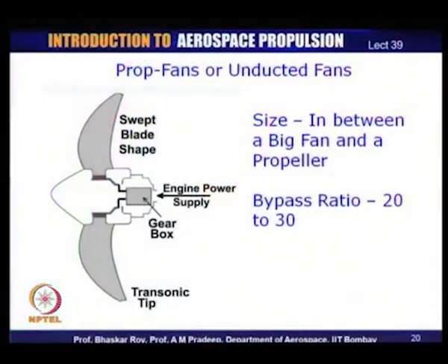You can see the shapes that have been developed, and some of these have been around for 10-15 years. These are becoming more and more efficient. The designers are working on them, and they are getting more and more exotic shapes to create more efficiency. But the fundamental fact that a very high bypass ratio gives very high fuel efficiency is the biggest attraction, and that attraction is what has kept them alive. Now, it looks entirely feasible that in a very short while we shall see these prop fans operative and flying aircraft, especially subsonic civil aircraft, all over the world.